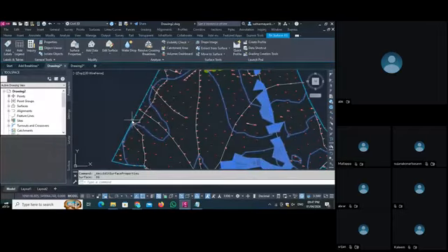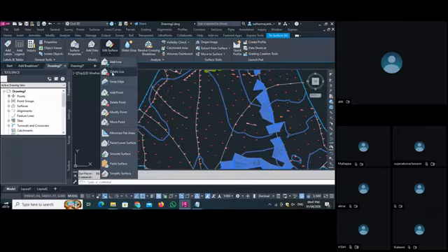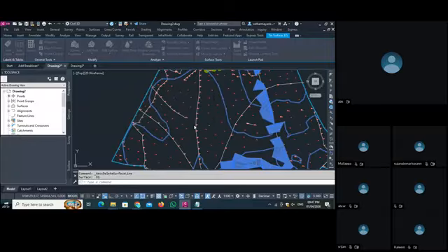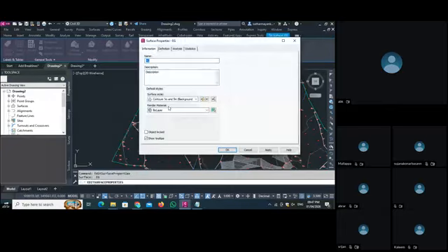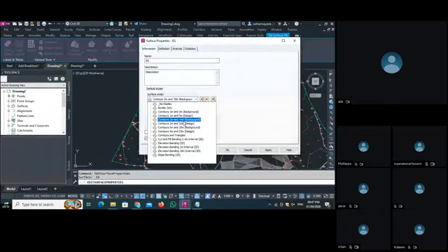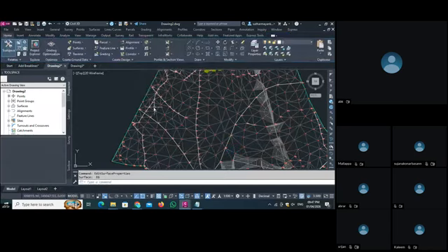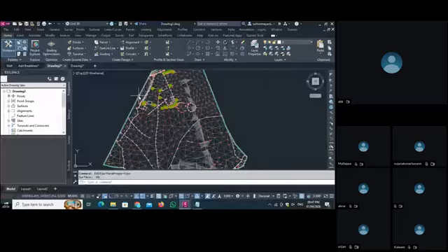I again select the surface, go into edit surface and want to delete a line. As I select, Civil 3D shows me that you must have triangles displayed for this operation. Edit the surface style and try again. So for editing your contour, you must set your properties to contour and triangle. Now you can edit this triangle.